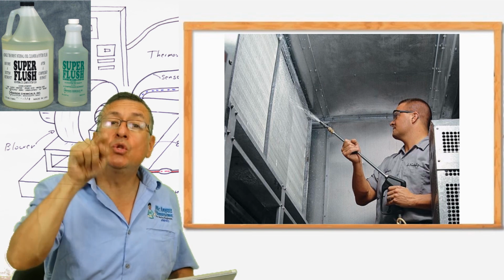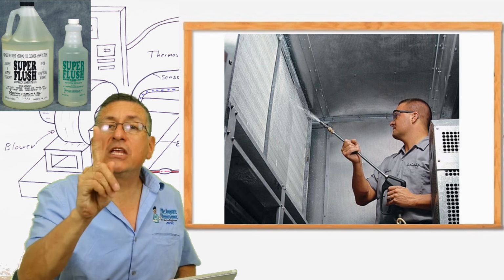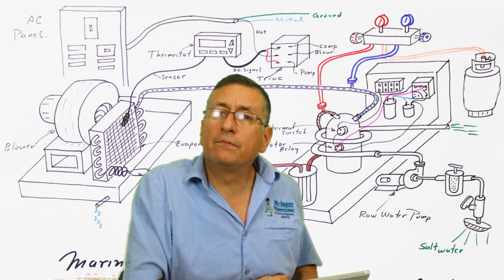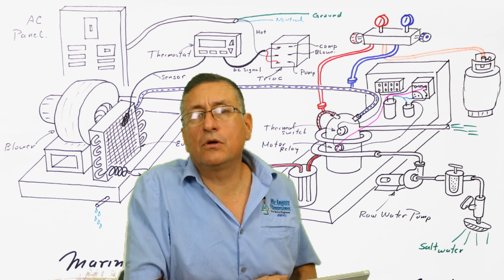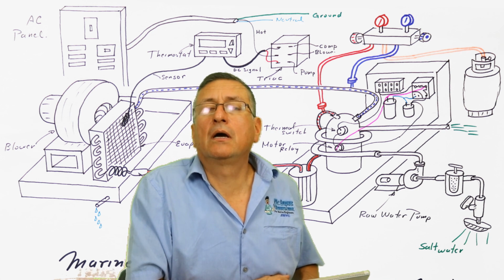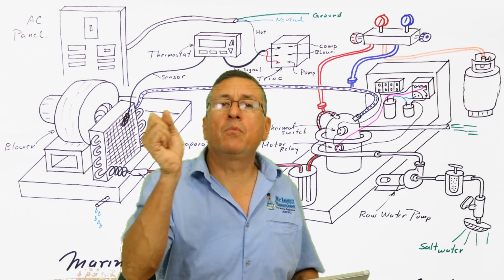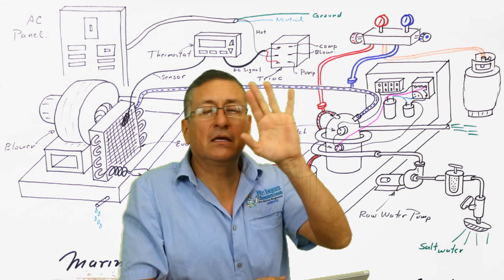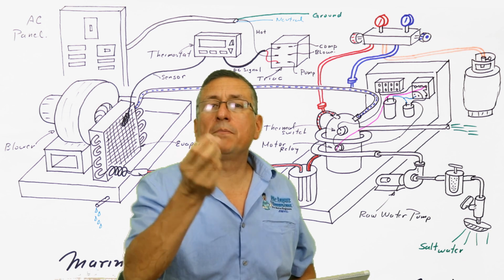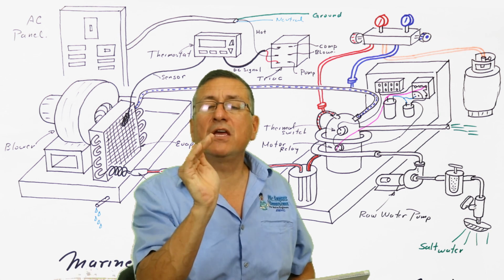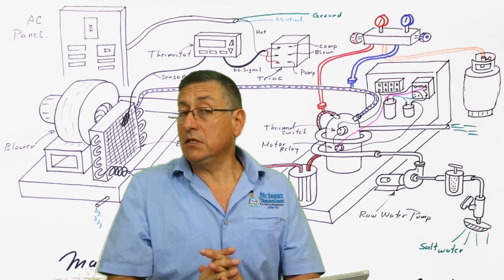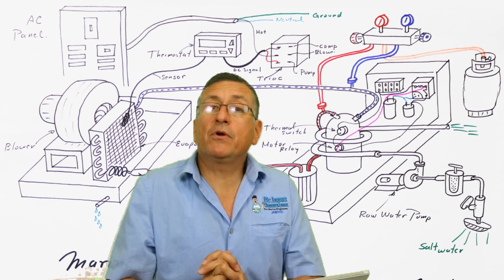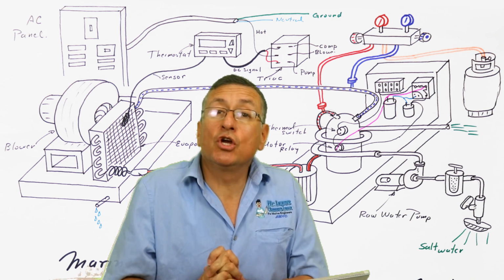I recommend doing that process once per year. Normally in my home, during the winter, I clean the evaporator with bleach, water at high pressure, and the blower after that. Yeah, and I eliminate all the debris and particles in between the fins of the evaporator. This is the typical way to check if the evaporator is working in good condition.